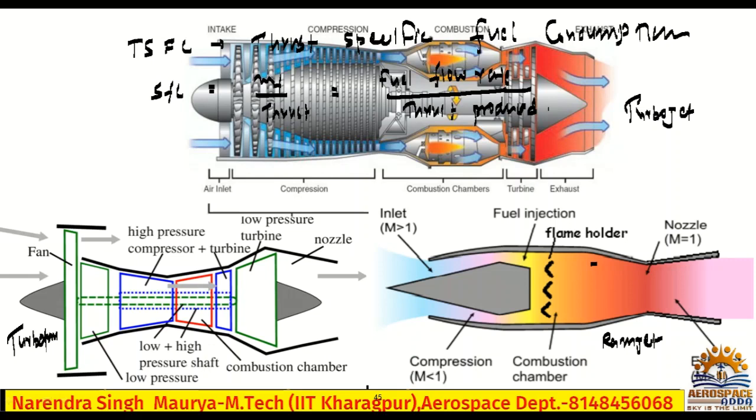They have clearly mentioned the same thrust. So now your SFC, as per your formula, SFC is nothing but m dot f divided by thrust. And here thrust is constant for all. It is clearly mentioned in the problem. Anyway, they have said the same altitude, so all the atmospheric conditions must be the same.